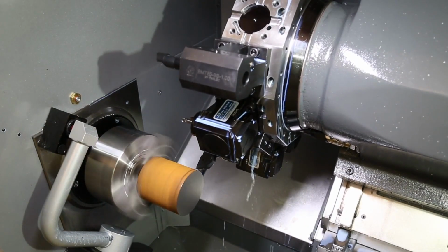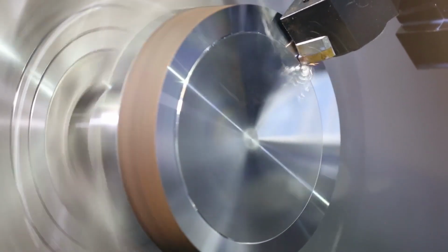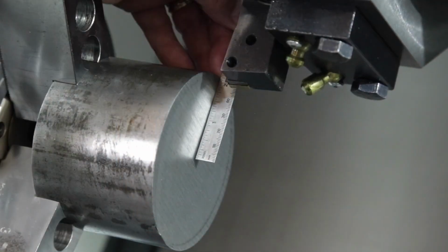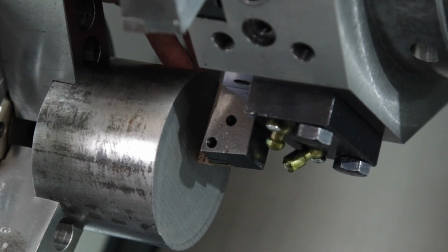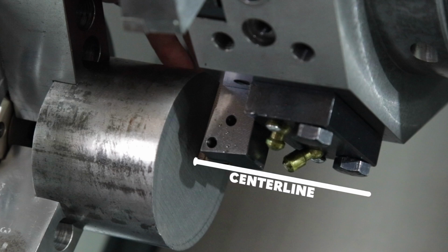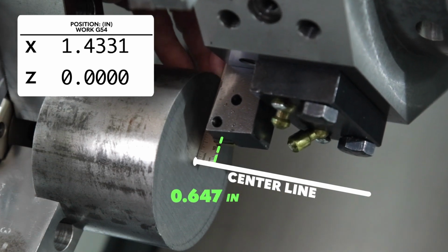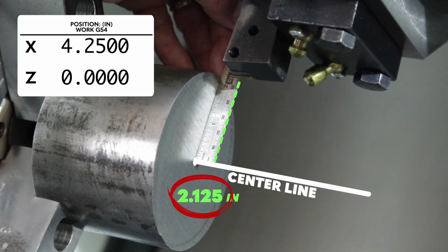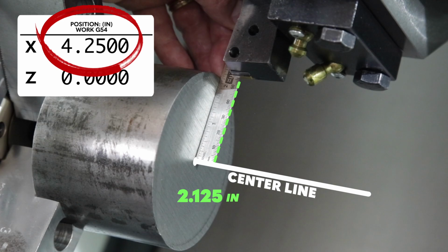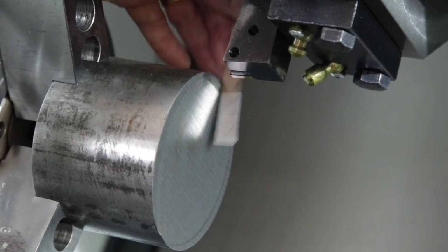The reason for this is because the workpiece rotates about the spindle center line, but our cutting tool stays on one side of the spindle center line. I'm going to hold my scale here, stationary against the workpiece, with the end at the spindle center line, which is 0 in the X-axis. Now watch the readout on the control as I jog the X-axis. You can see that I jogged the X-axis 2.125 inches, but the amount on the display is showing 4.25 inches, twice as large as the actual movement here on the scale.